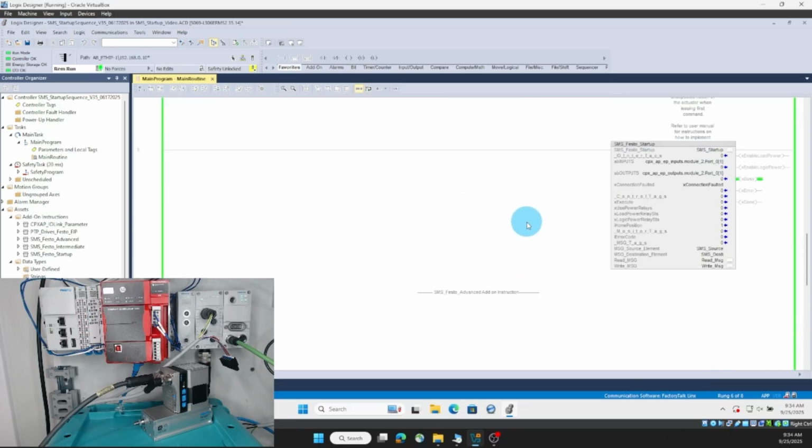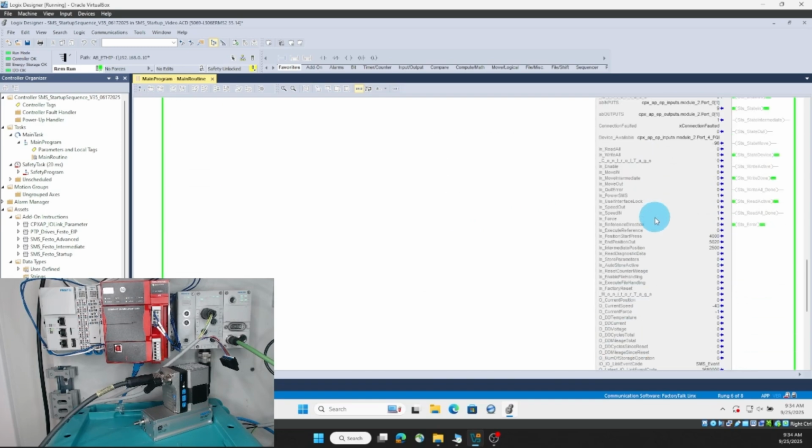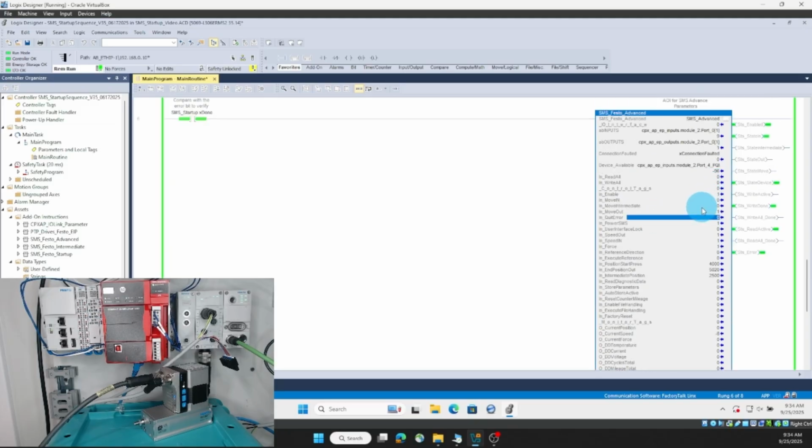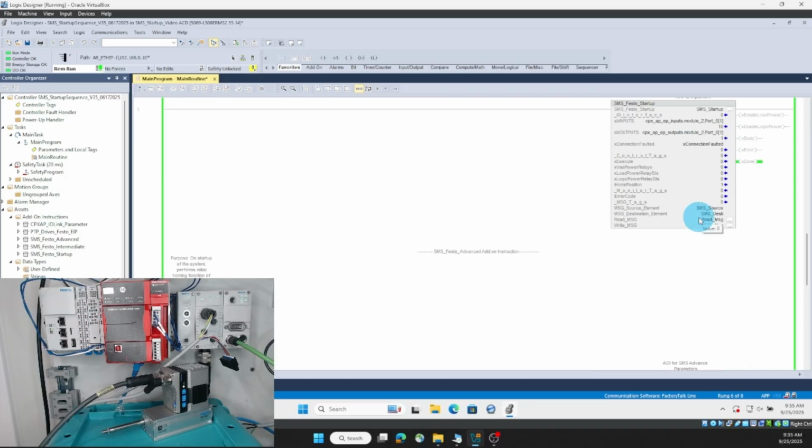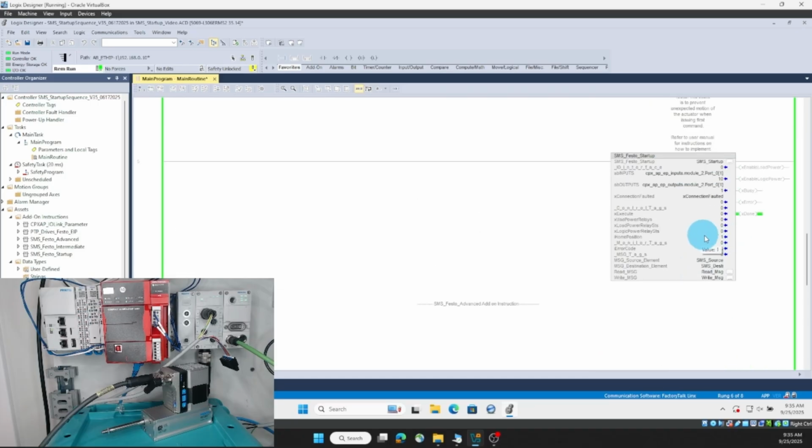Now technically this startup routine is going to run right away, but we're not going to see the intended motion yet. So let's first go to the original AOI. I am going to move this position out. After clearing the error. So now I'm going to perform a power cycle, and the expectation is that this is going to perform the initial move in and end in the in position.